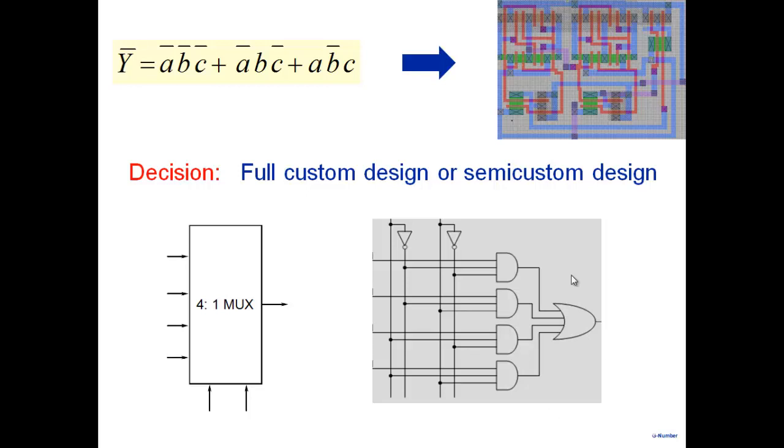And so for this particular problem, it has many more gates than are necessary, right? And obviously it is then complex and it would occupy more area, right? So it's not an optimal design. It's very convenient. You take a mux and apply the inputs and your design is ready. But it's a non-optimal circuit, especially in terms of area.